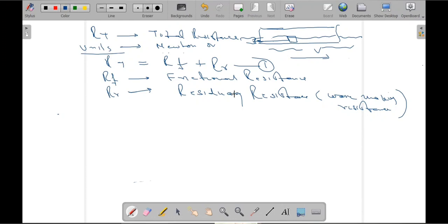Wave making resistance or residuary resistance means that as the vessel moves, some waves are created, and we are not talking about the waves created because of wind or swell or any other thing. They are external forces. We are at the moment only concerned with the waves created because of the movement of the vessel, even if it is a lake, correct? You must have seen while going in a boat in a lake, as the boat moves, still you have waves created. So let us not confuse this with the waves because of external forces. We are talking about the movement of the vessel.